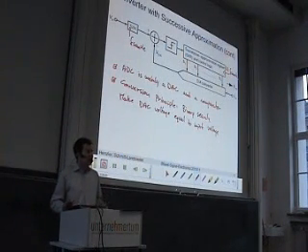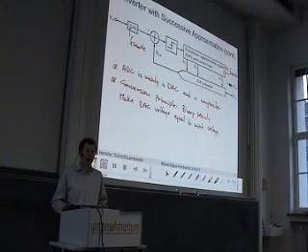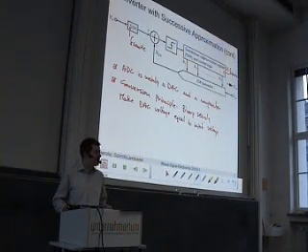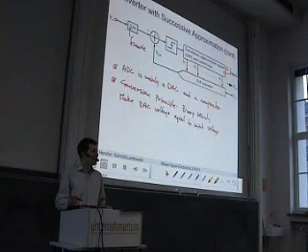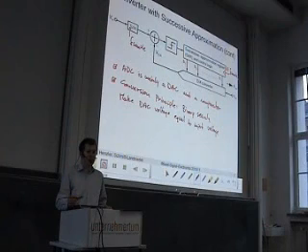And if you think back to the overview slide that we had last time, and we said there is a successive approximation converter, which is a device performing a binary search technique, then you understand why this converter is for medium frequencies and not for very high frequencies.